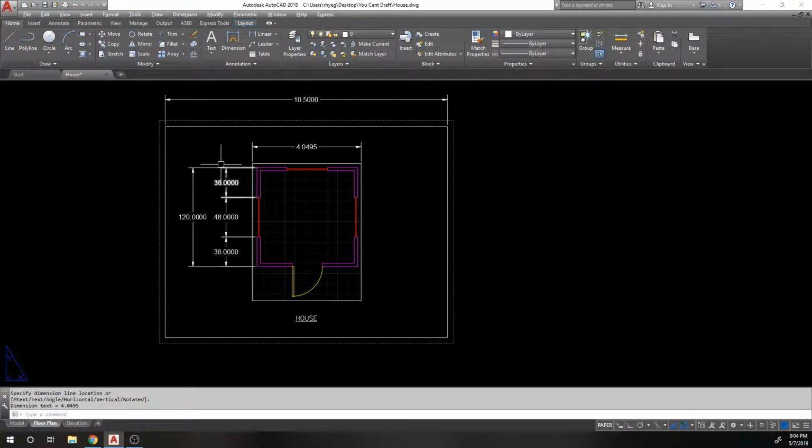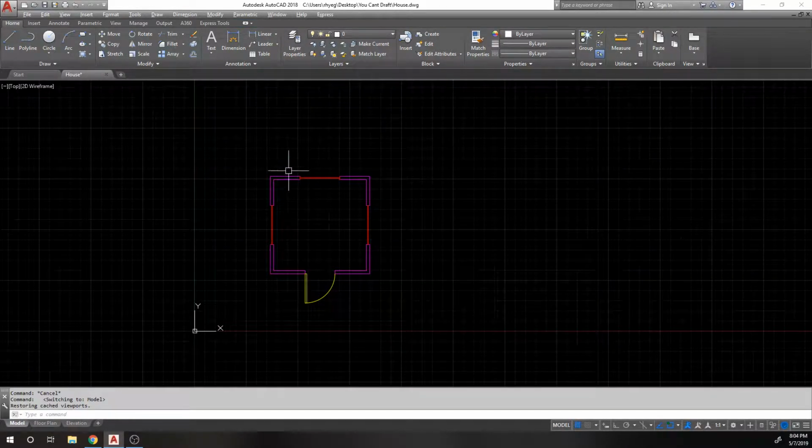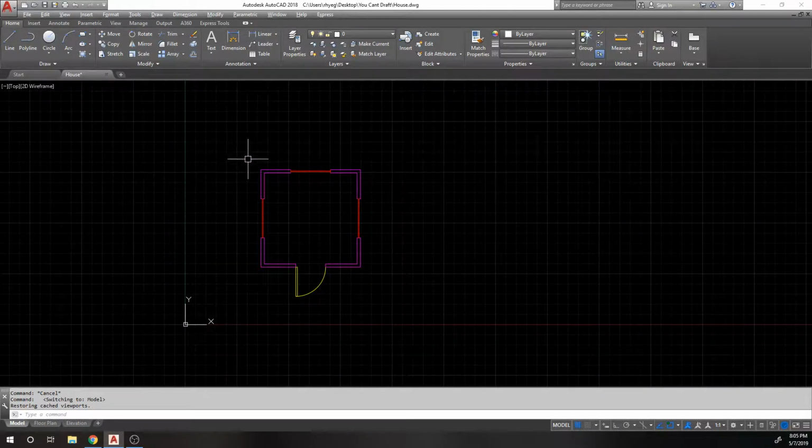So everything here is on a smaller scale because we're working with a smaller piece of paper. Okay, if you draft in model space, everything has to be scaled up. If I want to print this and I want to annotate this in model space, I can't put in an 8.5 by 11 piece of paper. I have to scale it up. So in order for me to scale up, let's say I want this to be 3/8 scale still. Okay, bear with me here.